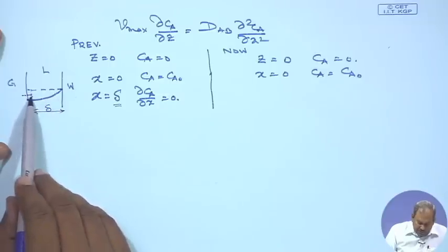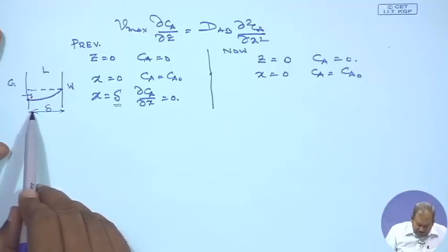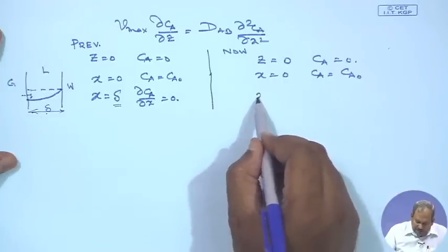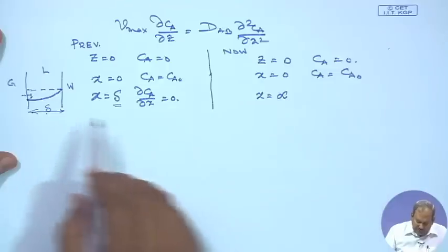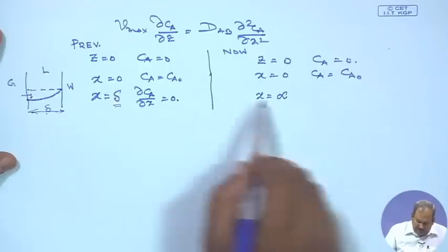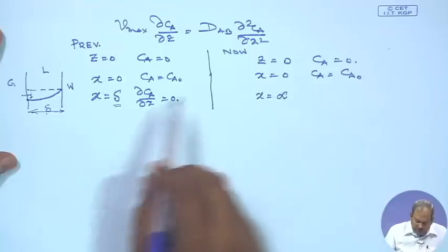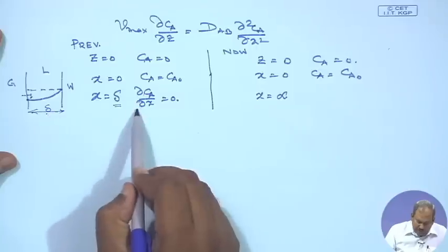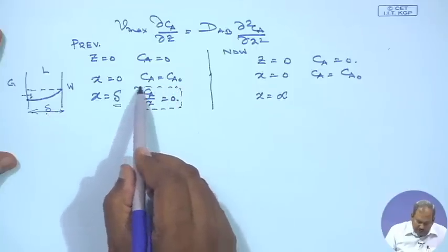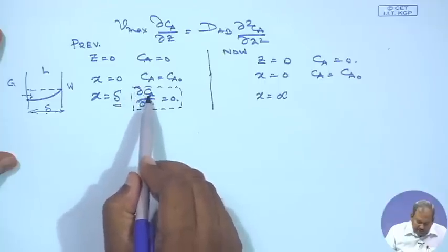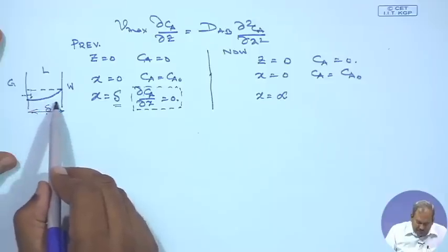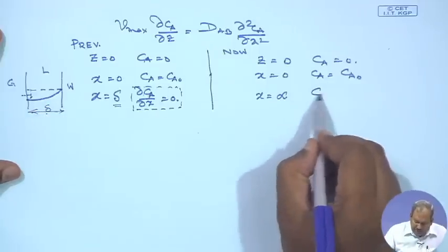So, the A molecules cannot go far into the film; for the diffusing molecules this delta is close to x equals infinity. So, delta is essentially infinity to the diffusing A molecules. And what is the condition that we should use for x equal to delta? This equation is no longer valid, it is meaningless, since no A exists at that point. So, we will use the same condition as we have done for boundary layers, and I would simply say